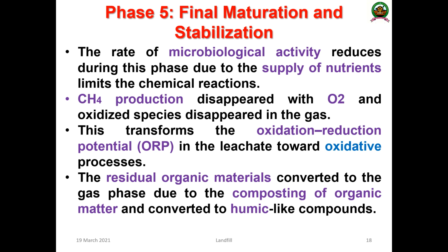The methane production disappears with the oxygen, and the oxidized species disappear in the gas, and this transforms the oxidation reduction potential in the leachate towards the oxidative process.